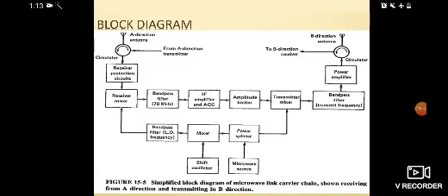And what is the use of the circulator? It allows the same antenna to be used for both transmission and reception, just like a duplexer. Whenever we have a duplexer, it switches between sections. It is nothing but a circulator which moves signals in all of the directions, so we can transmit the signals and we can receive the signals. So the circulator provides the same antenna for both transmission and reception, just the directions will be different for transmission and reception.